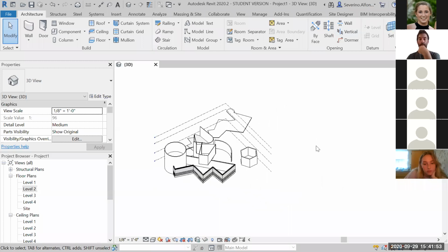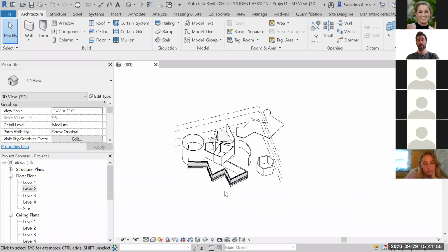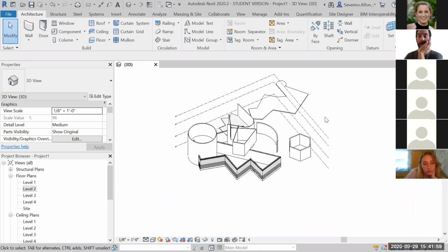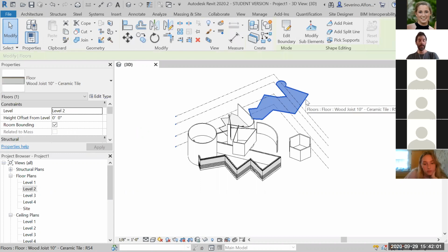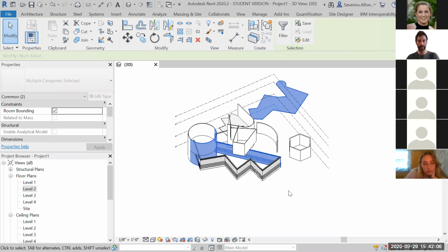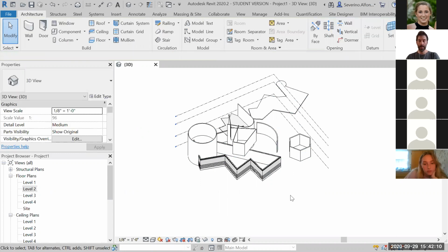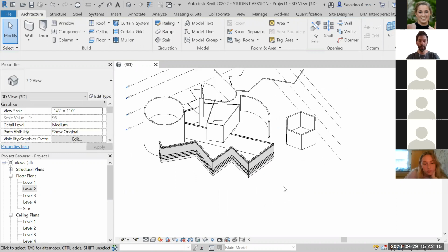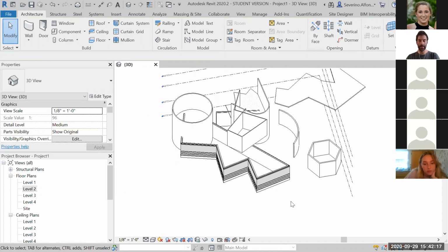Okay, more stuff. Selecting more, as in more different ways. Again, as I mentioned, you can select also in 3D. By pressing Control, you can add to the selection one by one. You can deselect with Shift, but there's another very important kind of a tool in Revit that allows us to select differently, which is by pressing Tab. And this, I'll explain it slowly, and I want everybody to try that.